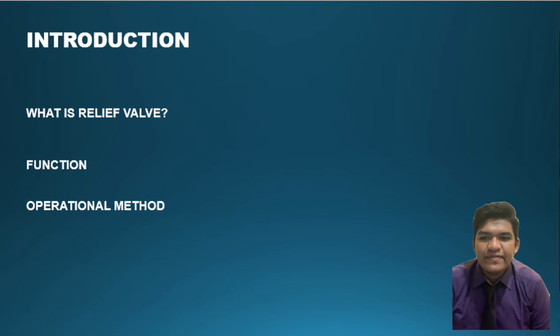What is relief valve? Relief valve has a purpose quite different from the previous valve. They are designed to release excessive pressure that builds up in equipment and piping systems. To prevent major damage to equipment and more importantly injury to workers, a relief valve can release elevated pressure before they become extreme.